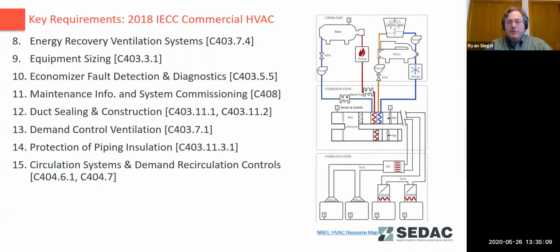I also have a question here about 7-story multifamily. Is that commercial code? The building would be a commercial, it would fall under the commercial provisions. There are some references when you are in residential occupancies that the commercial provisions will refer back to the residential provisions. So the building itself and the building envelope would be a commercial building envelope under the group R.